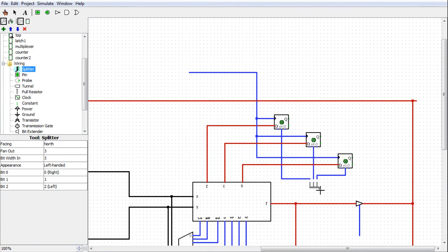So it's going to be sign, carry, and then the high order bit is 0. 0, carry, sign. Good. This is important because some operations you want to save the status bits, and some operations you don't want to save them, or you want to overwrite them, or you don't want to overwrite them. So it's important to be able to control that.